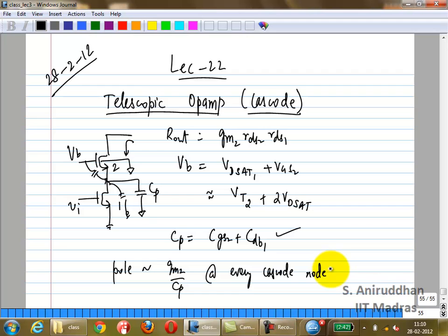So let's say you just had this transistor and you keep increasing the length. The parasitic capacitance will increase a lot more, so actually the pole will become quite small. That is something you have to worry about if you just work with a single stage op-amp. Whereas here you can create a very large output impedance while adding a somewhat prominent dominant pole. Okay, we'll need to see. Only if you analyze it, you'll see if it is really dominant or not.